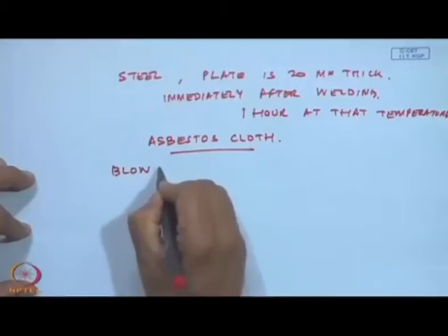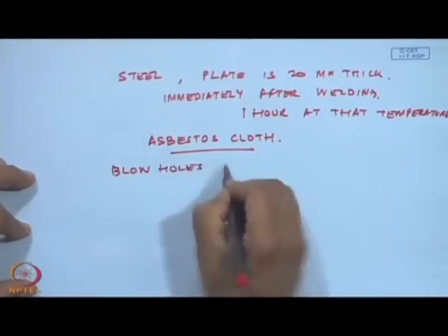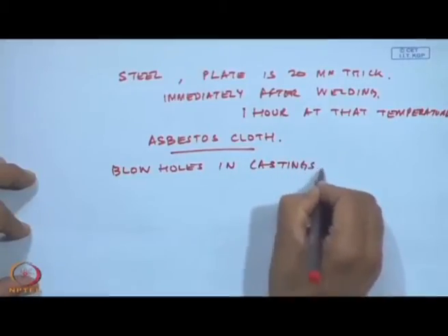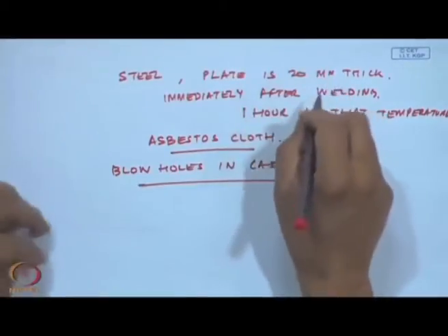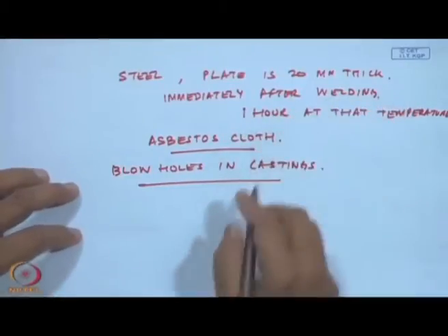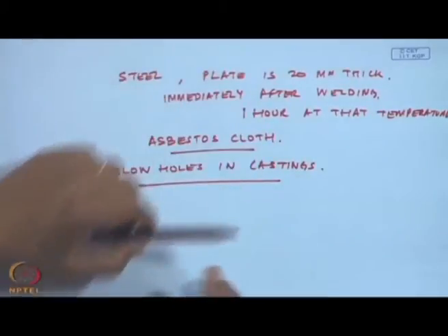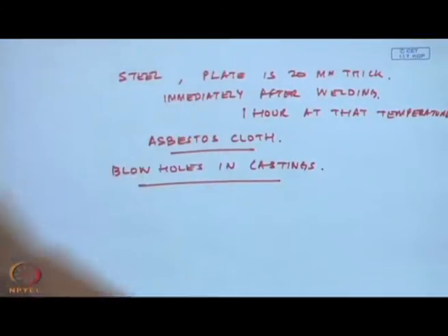Another reason, of course, that cracks occur is because of casting defects, blowholes in castings which go undetected, poor casting, and then of course, these blowholes etc. can be checked by ultrasonic testing.